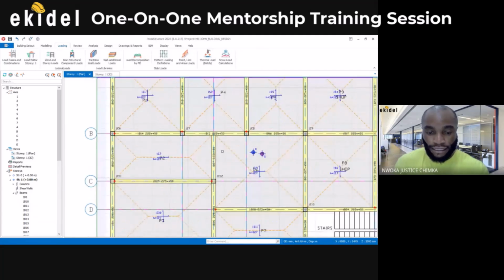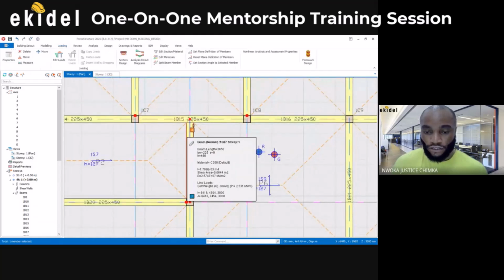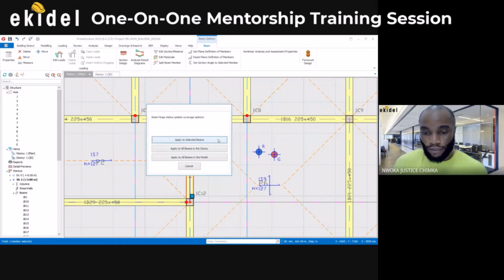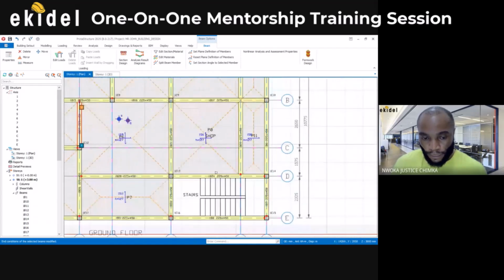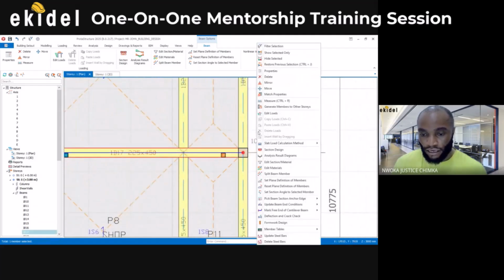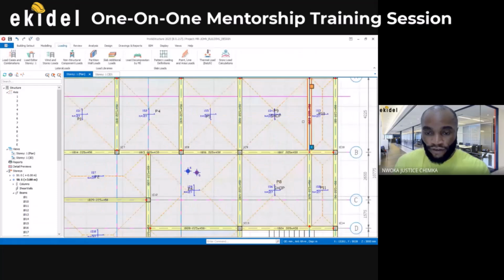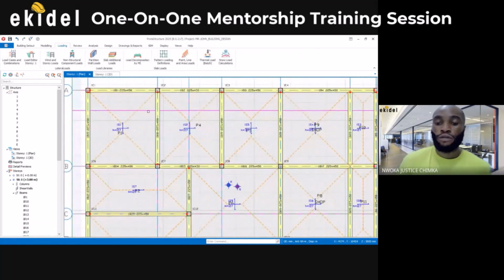Now you can see that there is something that we missed. This is meant to be at J. So I'll click and say J and then update. Again, let me see if I missed any of them. Okay, here also is missed. So I'll come here and right click. This is J end, so hinge at J. So just look again very well and see if you're missing one. So now it is best.